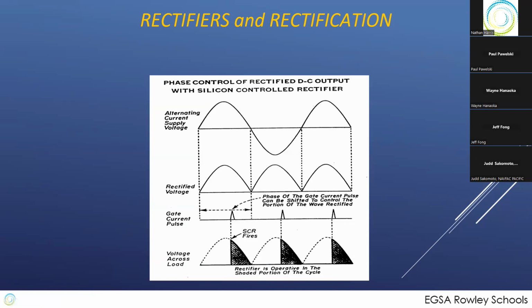Control systems. All right, when you're looking at older power plants, right now there's a big concern with EM pulses and how that's going to affect power on your bases. All of your standby power plants end up having to be put into a Faraday cage. Having helped design these, I can tell you right now it's a pain, because you need a large amount of air coming in for both combustion on the engine and for running through radiators for cooling. You also need exhaust gases to get out.